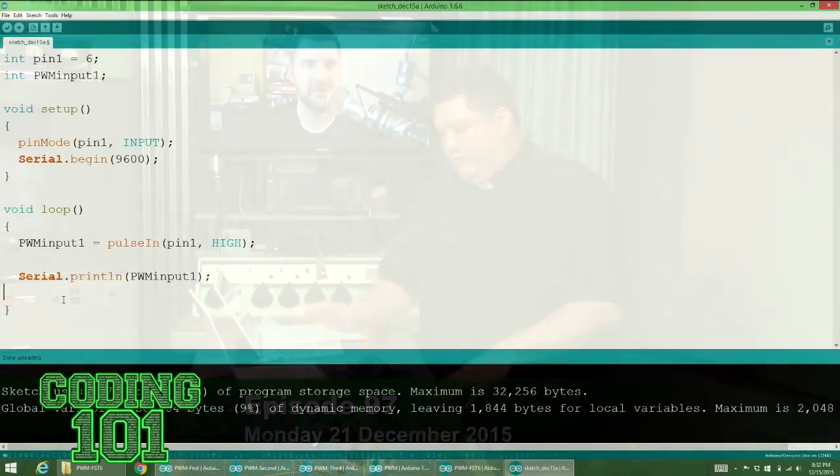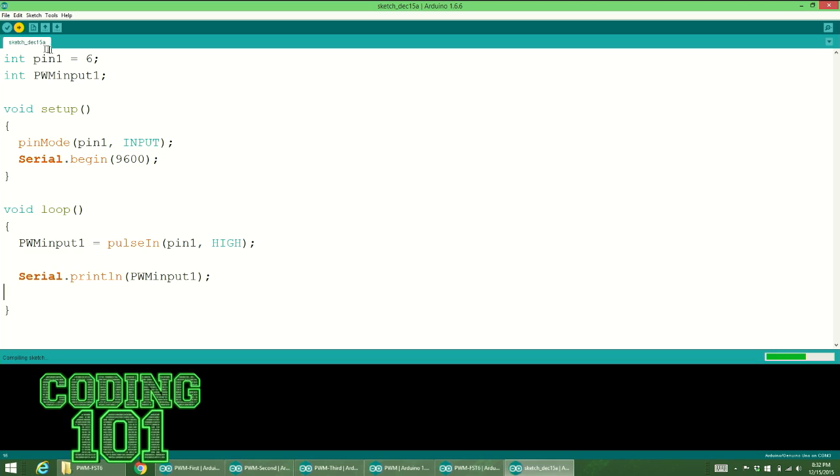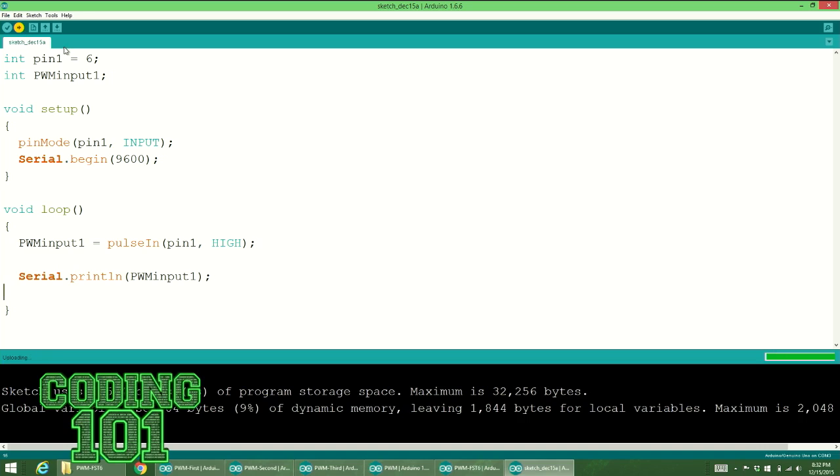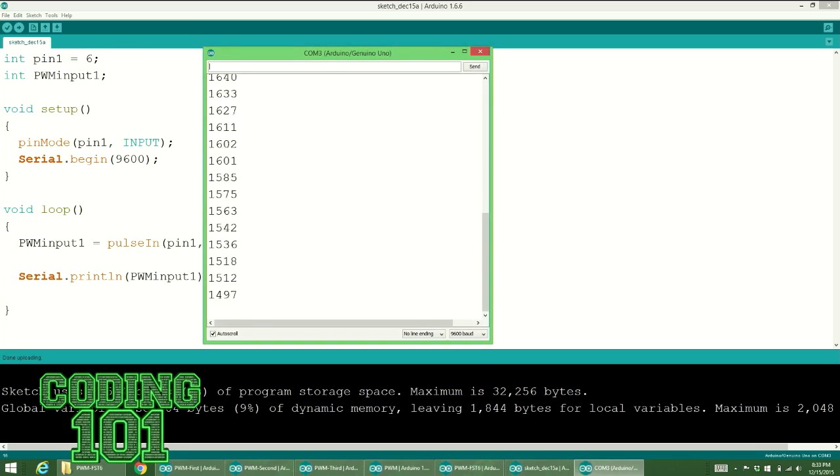But yeah. And actually, let me do one quick thing, because I know there's going to be people who are wondering why you put that delay. I'm going to remove the delay. So I've just deleted it. I'm going to go ahead and upload this again. Okay, it's uploading, and we'll see. Done uploading. Now let's go ahead and open up the serial console. And if I do this, see, it's just a mess. Yeah, so you don't want that to happen. That's why we put a delay. The delay is not really for the program, it's for me. I can't read the numbers that quickly.